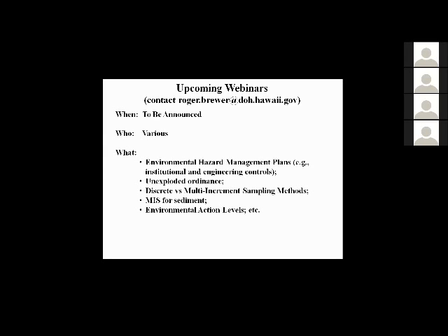Sounds good. Okay, had another question. Does a large number of points increase the risk of vapor intrusion? I think what they meant by that is, do you have a risk of failing? You're not going to actually cause vapor intrusion, assuming you don't have a leaky point. And depending upon what you're using, I haven't had trouble with the vapor pins leaking. But I think what they were really asking is, does a large number of sample points increase your risk of exceeding your soil gas screening level? And the answer is yes, it does, because it's a whole lot easier to pass vapor intrusion screening levels if you never really find the problem. But unfortunately, you do want to see the problem.